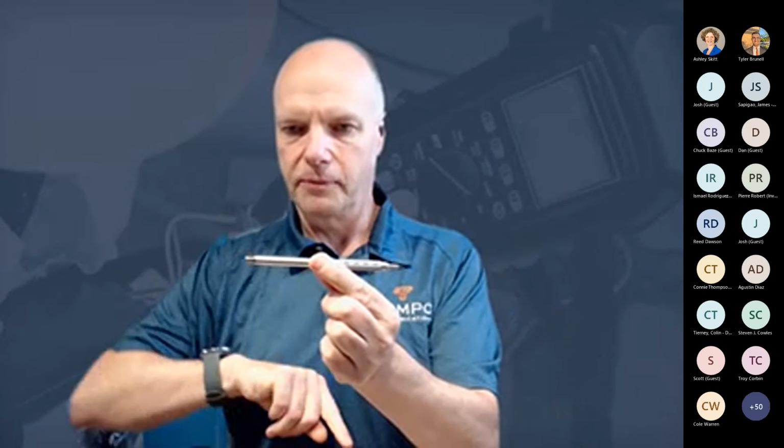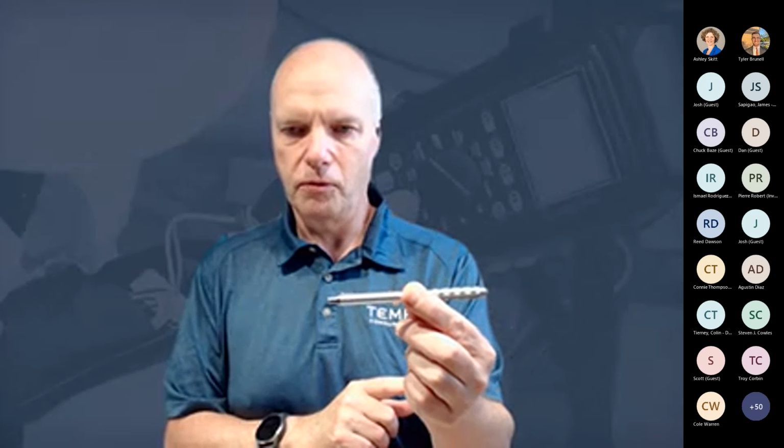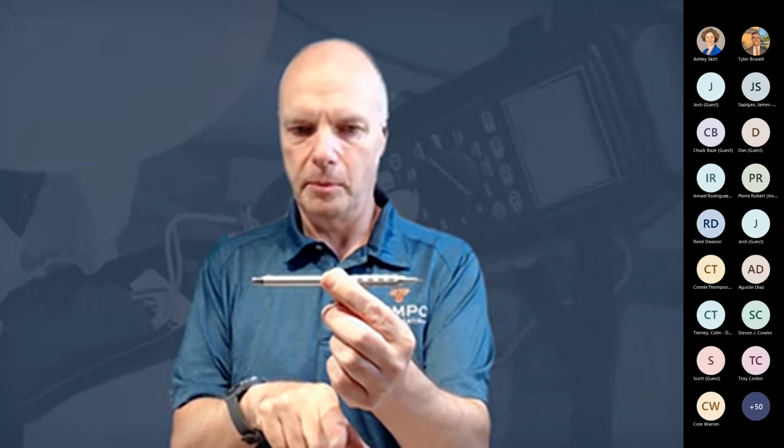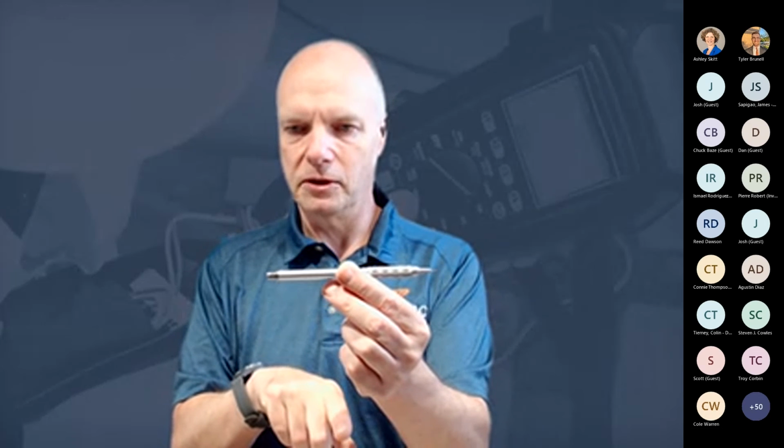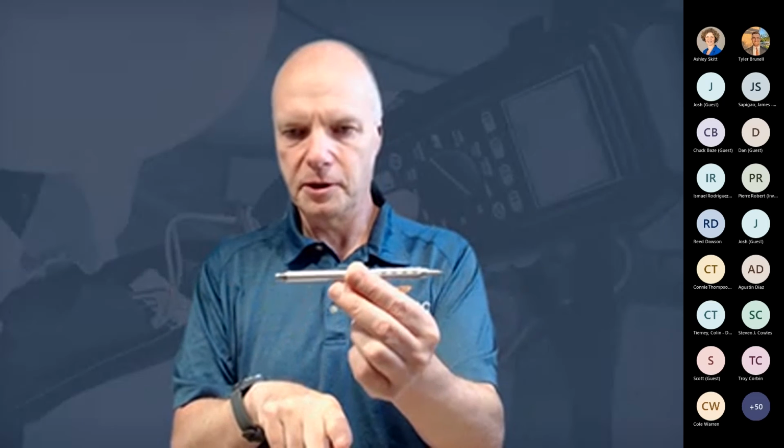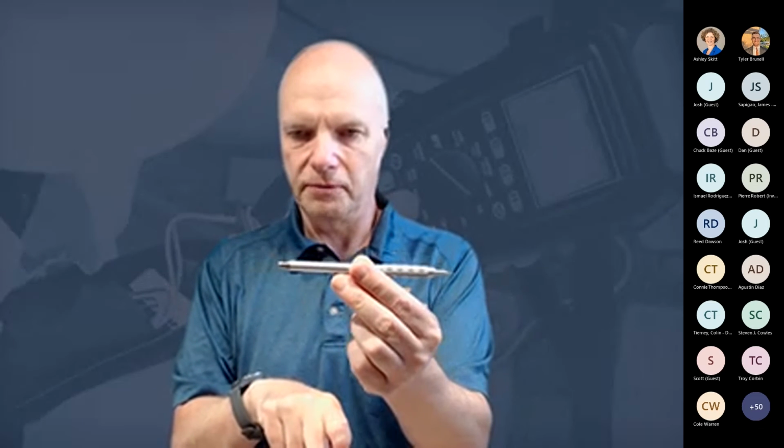If you imagine the cable is running from my chest towards you guys, and there's a current setting up a magnetic field around that cable, then when the coil is in this format, as you move the search coil over that wire and it comes directly above it, the maximum number of field lines will be coupling with that, so you'll get a maximum of signal, which will drop off gradually as you move off to either side. So there's a peak, but it's not super well defined.